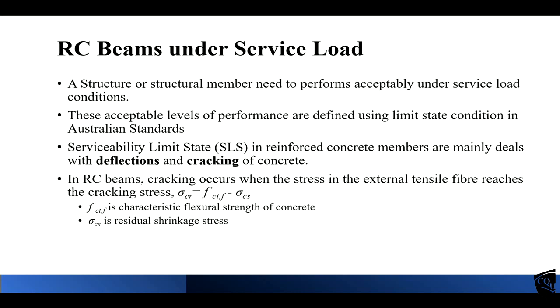Shrinkage means the change of length, or reduction of the length, over time due to two reasons. One is chemical reactions, the other is loss of moisture. The chemical reactions will happen within the first 5 or 6 days.